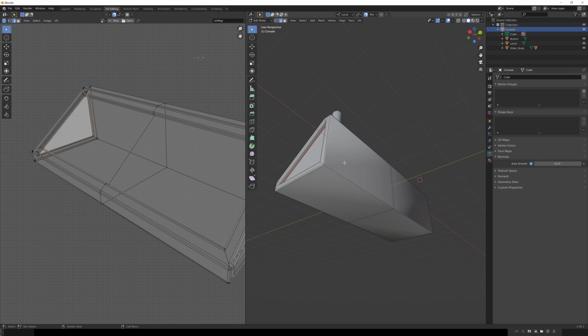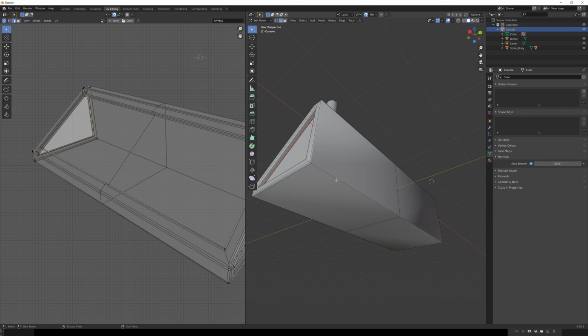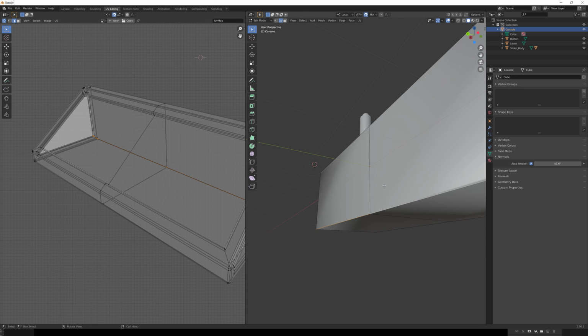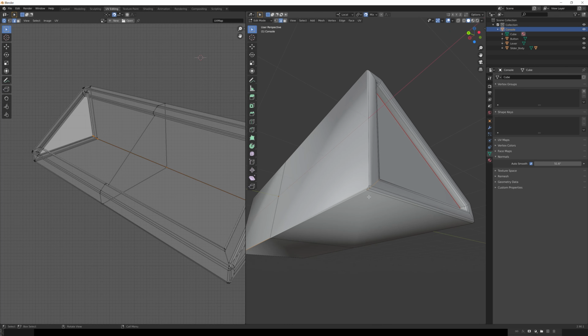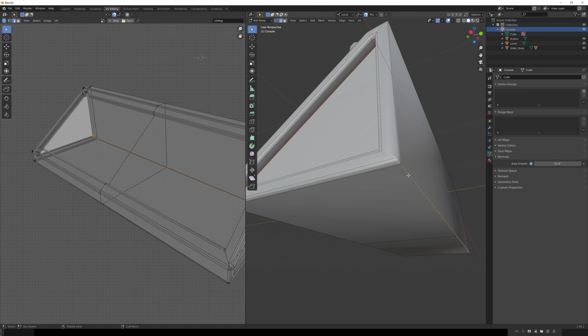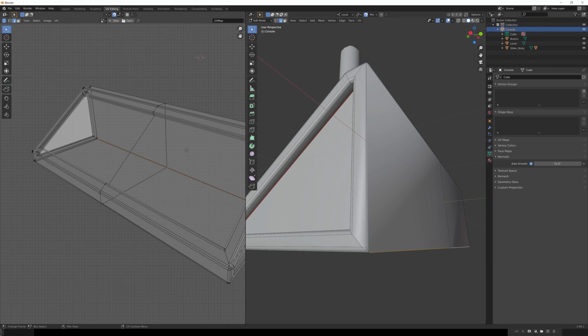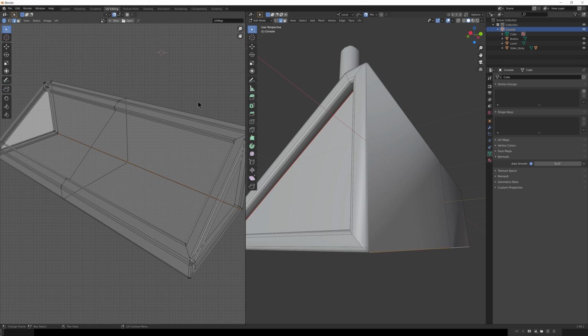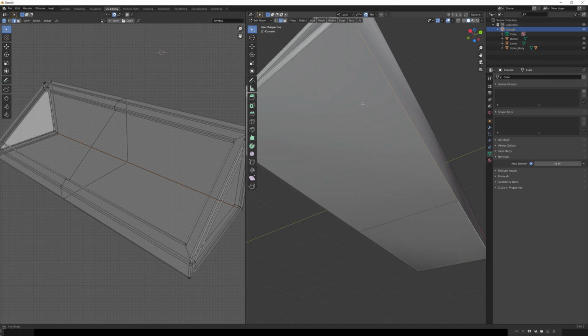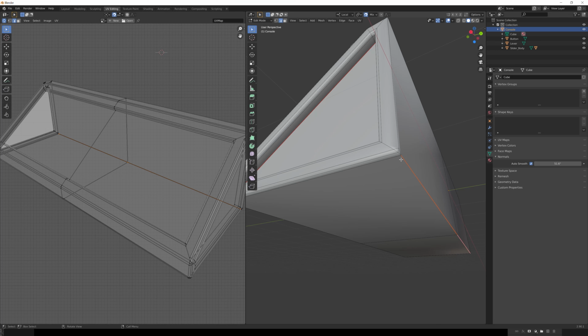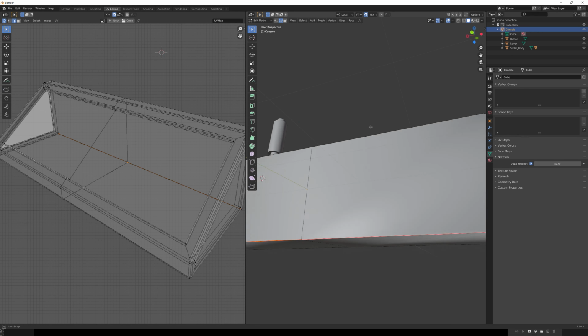But we've still got the back side of this, and that's probably the best place to introduce some seams. What you need to understand about seams is that from time to time, they are going to give you problems. In fact, let's select that one and that one. And what I mean by that is where you add seams can sometimes cause issues with your texture tiling or looking right, depending upon what you're doing. Let's right click and mark that seam. So now this can come apart here, but we've still got to make a decision on these edges to figure out how to unroll this entire thing.